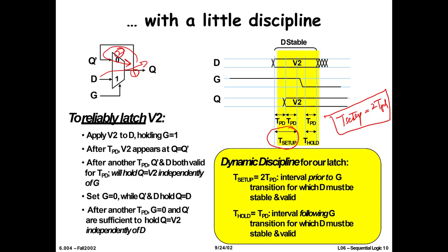Okay, so if you want the latch to reliably store whatever you want to store, you should apply that information before the clock edge. So here is your clock edge. How much before? At least 2 TPD time before the clock edge.